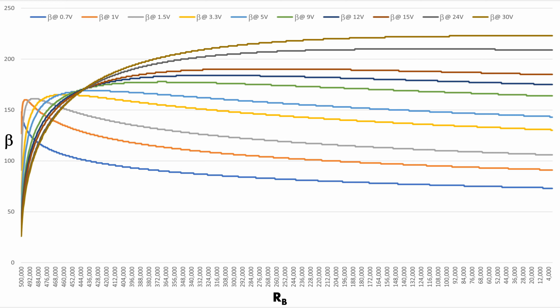It is important to notice that values for beta change dramatically when base current is very small, very close to cutoff current, regardless of VCC. For the smallest change in base current, beta rises exponentially. As the base current rises, or to be more precise, when base current approaches saturation values, beta tends to be less volatile in its value.